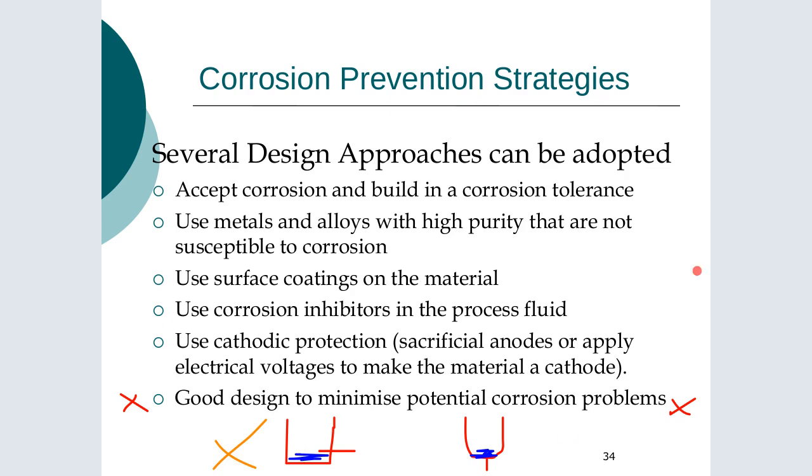And the other one then is what will be good, because you're having a free draining surface, free draining exit here, whereas this one you have a stagnant region. So no matter what you do, you'll always have material down the bottom, and it will sit there, and you have an opportunity for the reactions to it. So again, avoid thermal gradients, where you may form condensates from the environment. Avoid bends, or if stuff is going to drain, that stuff doesn't pool in particular regions and things like that. So there's a lot of design stuff that you can do that will improve your corrosion susceptibility.